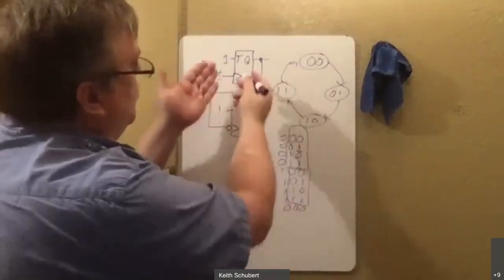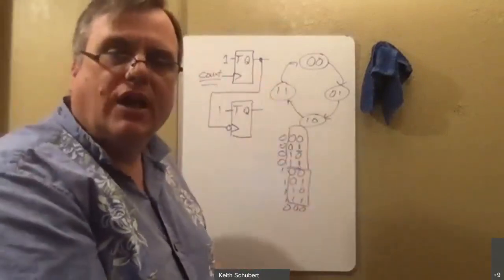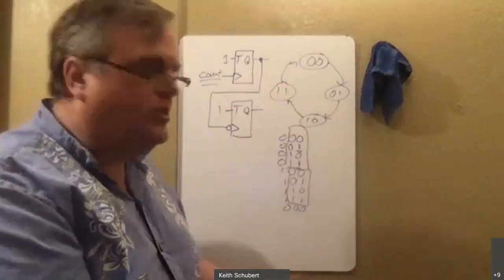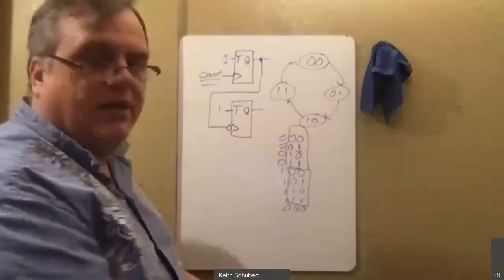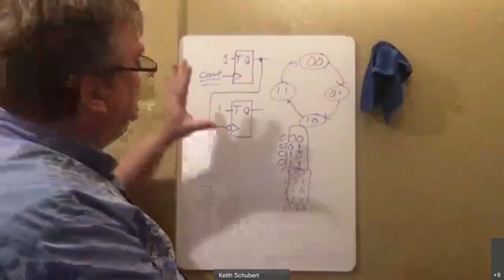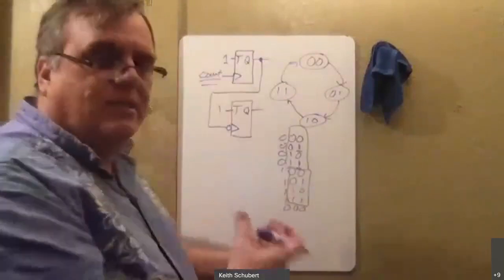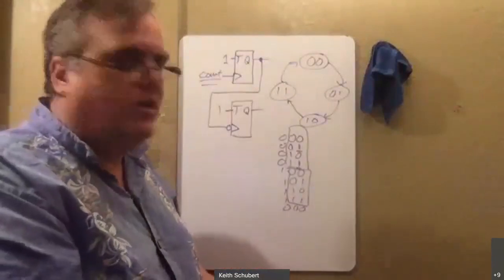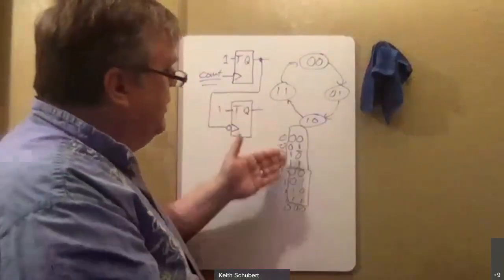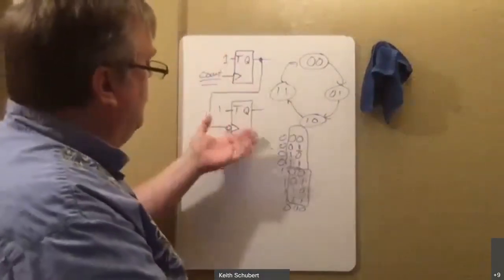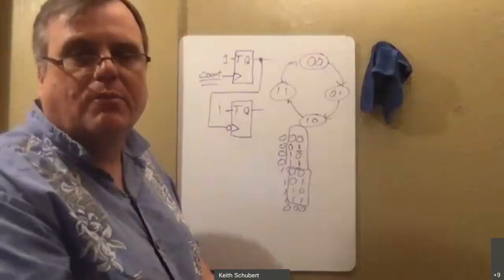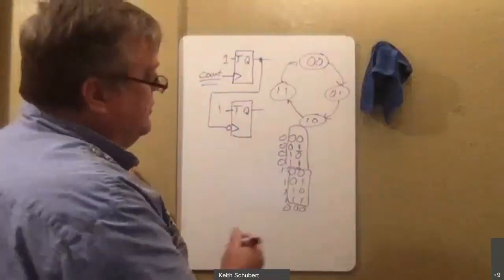What I have here works great for the first 2 bits. I only have to add some extra logic to handle the 3rd bit. The niceness of this design is it's really easy to keep building each successive layer. You can go to the next one with a very simple addition. Keep what you had before, add something else on top of it. So that's the advantage of it.